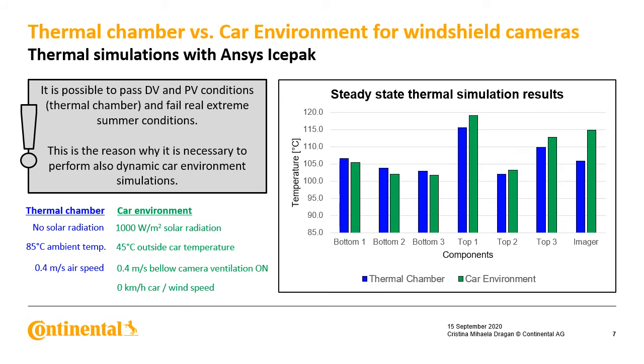This means that it is possible to pass TV and PV conditions in the thermal chamber and fail real extreme summer conditions. This is the reason why it is necessary to also perform a car environment simulation, and this time a dynamic one.